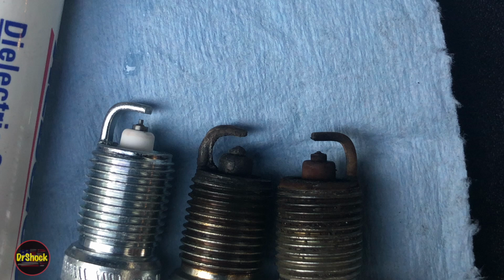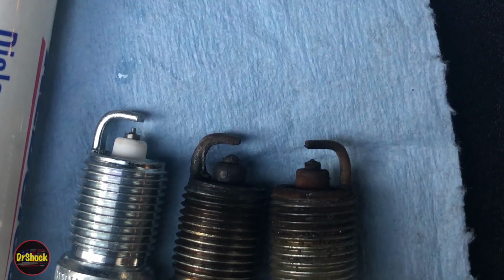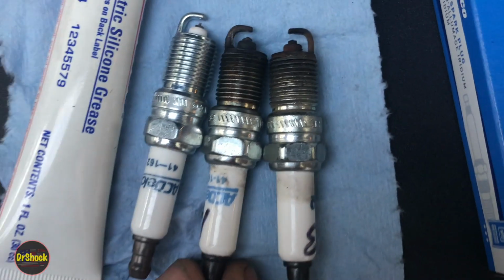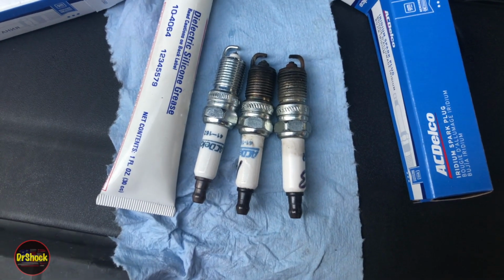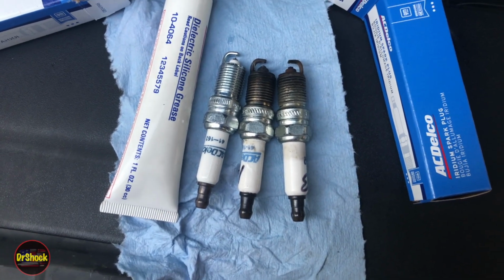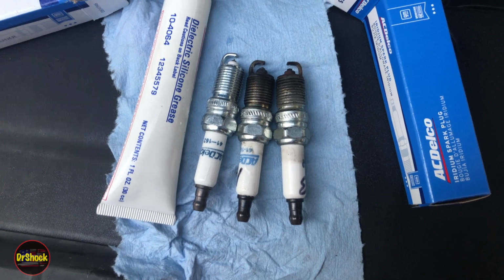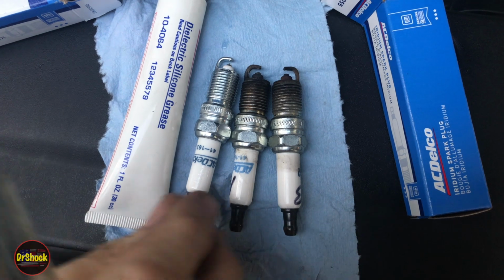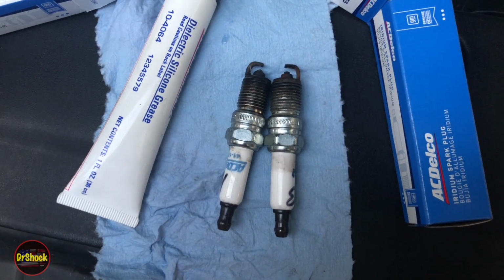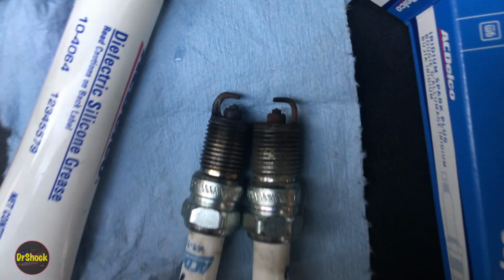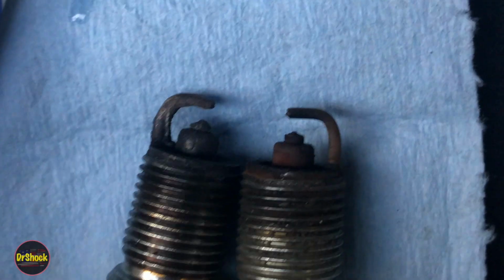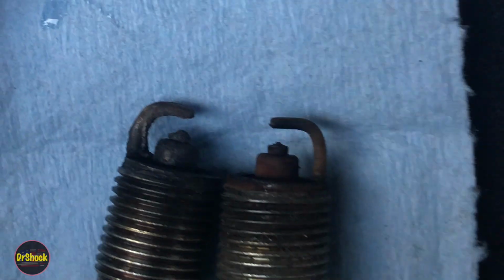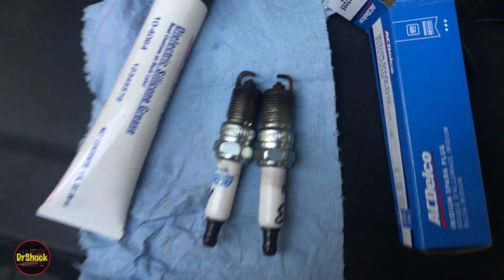So plug wires, proactive, that was a problem but not the problem. Fouled and burned plug, which is the reason for the misfire. Sometimes it doesn't have to be complicated. Sometimes it can be that simple. And then number 3 we changed proactively just because it looked like it was going to be the next one to suffer that fate. The others had very well-defined tips, and I did not feel that they were warranted replacing just yet. Again, this had new plugs just a year or so ago.